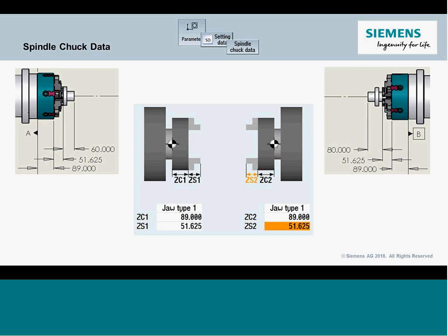And we went through this again in a lot of detail in the previous webinar, so just make sure you reference that. You've got to make sure that the chuck body and the projections are all known here, especially when we go to do the handoff, start working on the back, counter spindle, it uses all these numbers to calculate, and it'll actually write the work coordinate for 55 for you. You don't even have to touch it off, but you do need to have some valid numbers here for this all to work properly.